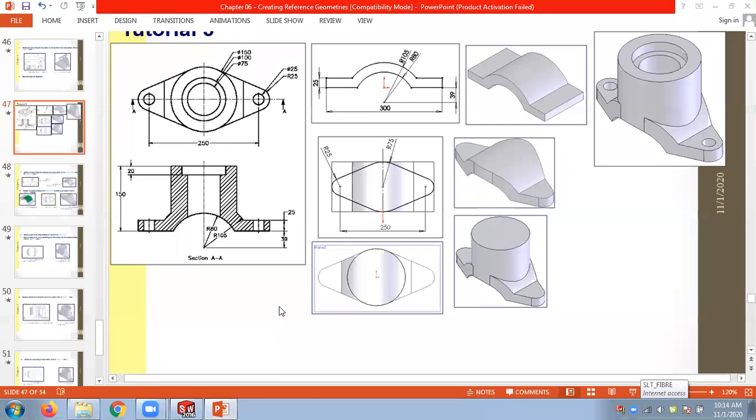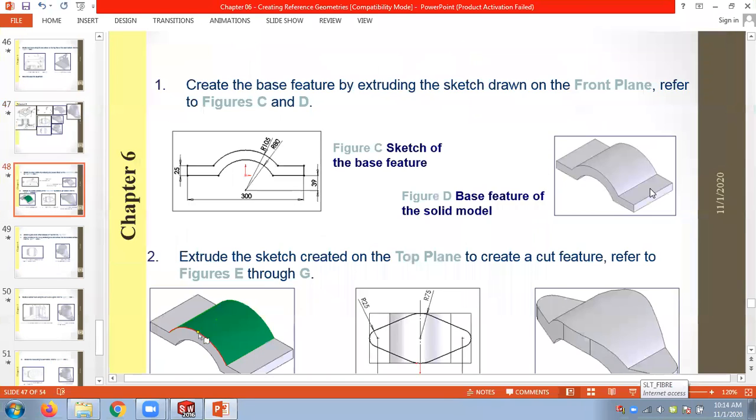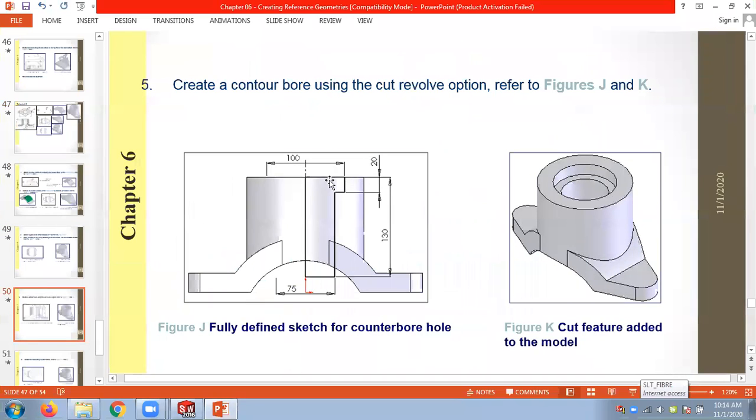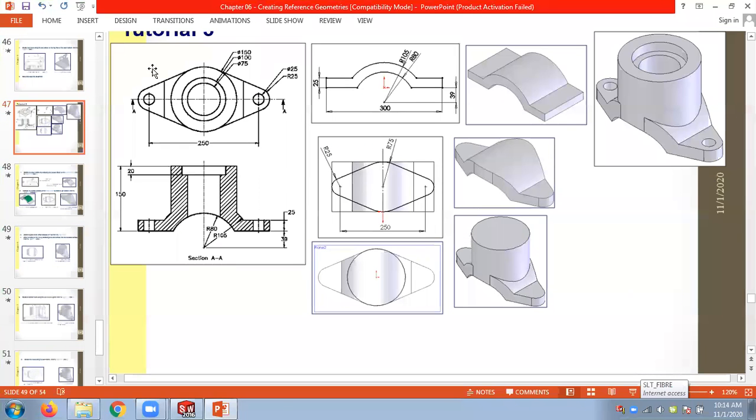Okay, we will cut inside now. So I have to get this shape. One way is we can apply 2 extrusion cuts, or else they have used the Revolve Cut. So if you want to apply Revolve Cut, it's one operation. I will first show you how to apply Extrusion Cut and do this. So we need to have 2 cuts here.